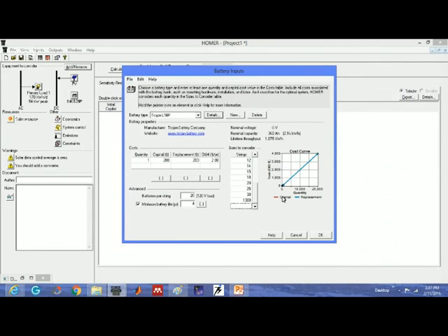So let's say you want to give any random value to the batteries, that I can afford any battery. See, number of batteries increase, the cost will increase. Both are contradicting. Number of batteries increase, cost increases. So we are going to minimize the thing. And sometimes the system is not feasible, so don't worry, it will give you a warning that the system is not feasible. Either you increase the size of battery, or you put a backup, you increase the size of photovoltaic, or reduce the load. It will say something like that.